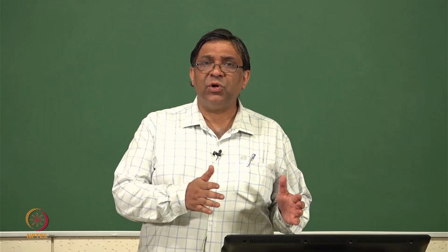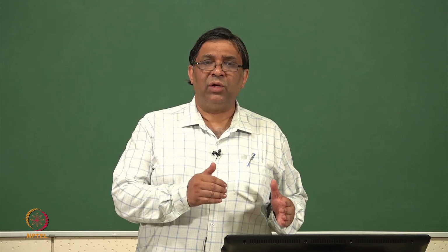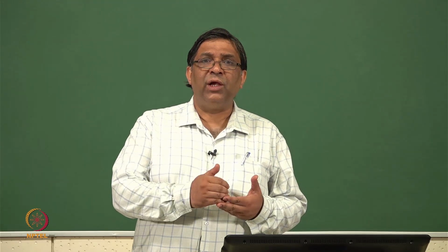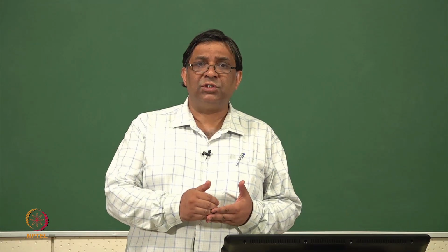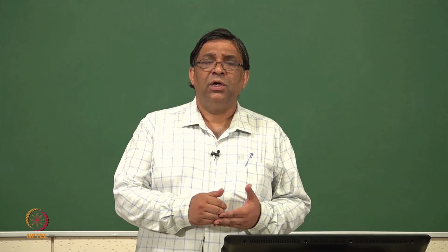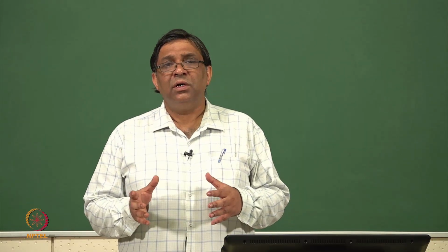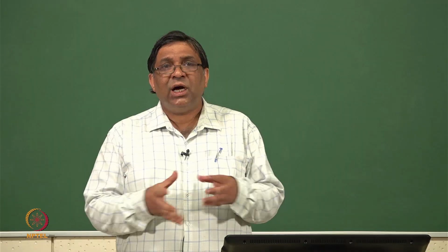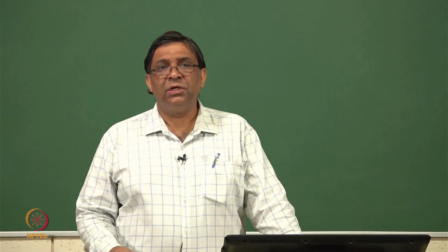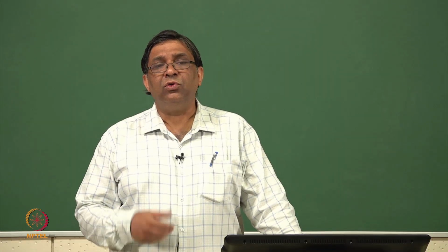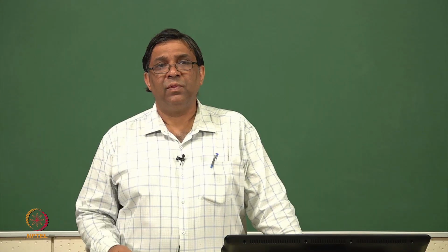So we have discussed recombination also in the last lecture. If you remember, we have discussed band-to-band transition, we have discussed Shockley-Read-Hall, we have also discussed Auger recombination. So if the recombination increases, then eventually the charge carriers which should flow outside the circuit are reduced, and therefore you do not get the voltage which you are looking for.